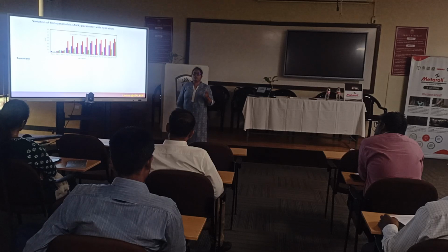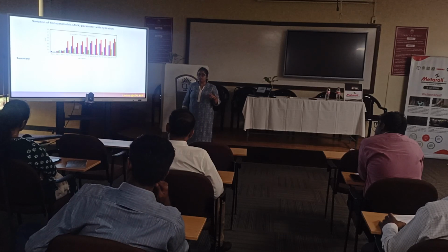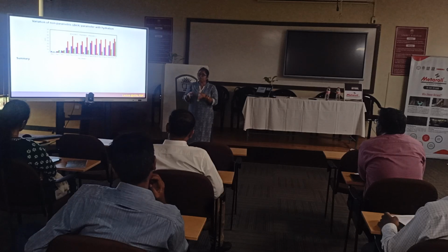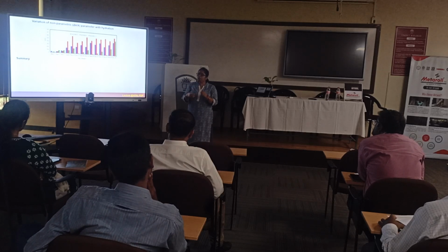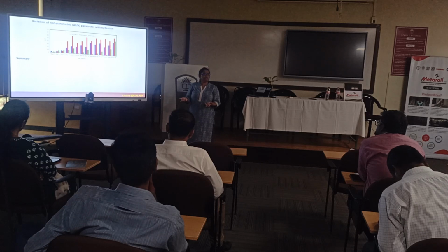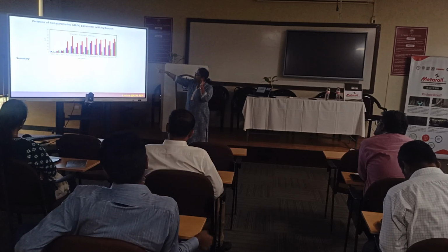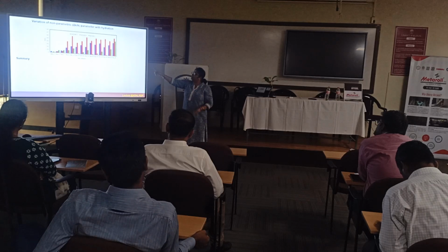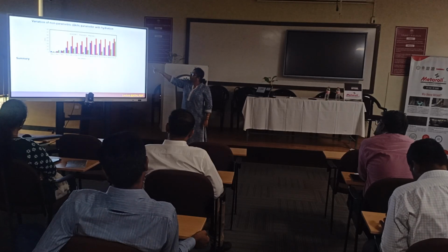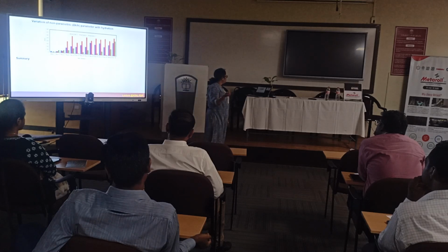How does it happen? Concrete has autogenous healing, because the lime is there, and lime is a reactive element. Whenever it gets CO2 and moisture, it automatically reacts and forms cementitious material. So autogenous healing is already there. That is why specimen 3 doesn't behave well initially, but from day 21 onwards it performs better towards the sensor diagnosis.